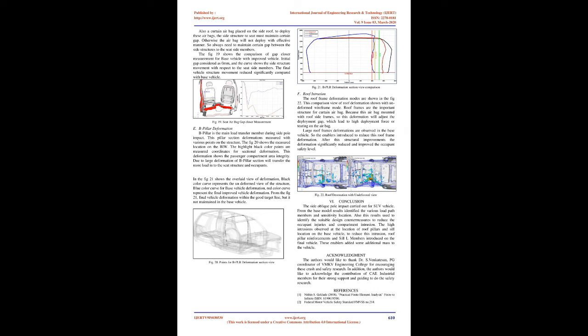C. Underbody deformation. The underbody view of the vehicle is shown in Fig 17. Right side picture is for the base vehicle and left side picture for the improved vehicle. In the base vehicle, large deformations are observed in the frame at the fuel tank cross member location, and frame bending led to a catastrophic failure of the body structure. These failures are improved by the side pole impact enablers, as shown in the right side contour.